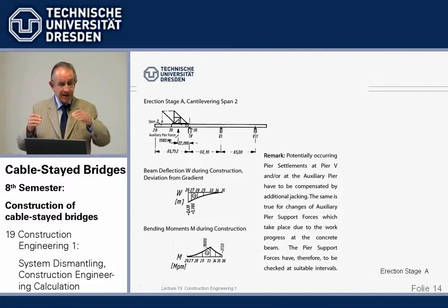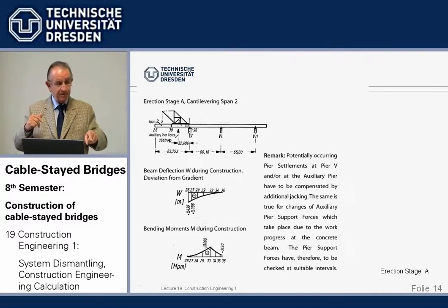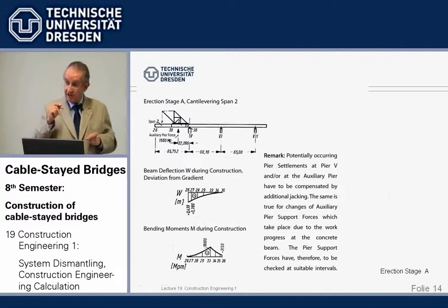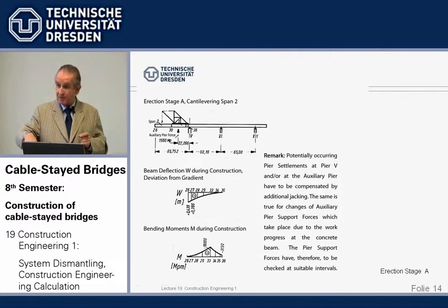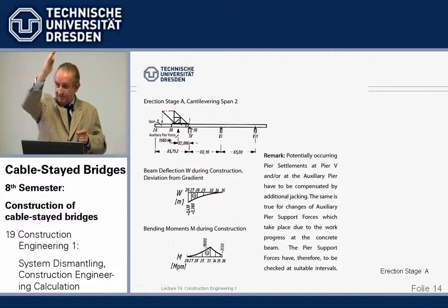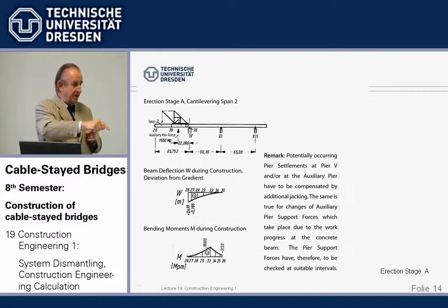And we can check the deformation by a theodolite, just by surveying. We can check the tip movement, and what is very helpful, by the way, we can check the tower head movement by putting on a plumb bob and load. Now we do it with a laser, but you know what I mean. Down, and you can measure the deviation of the tower head, and that's like a very, very long indicator. That's very helpful. Checking the tower head deformation, checking the beam deformation, and checking cable forces.